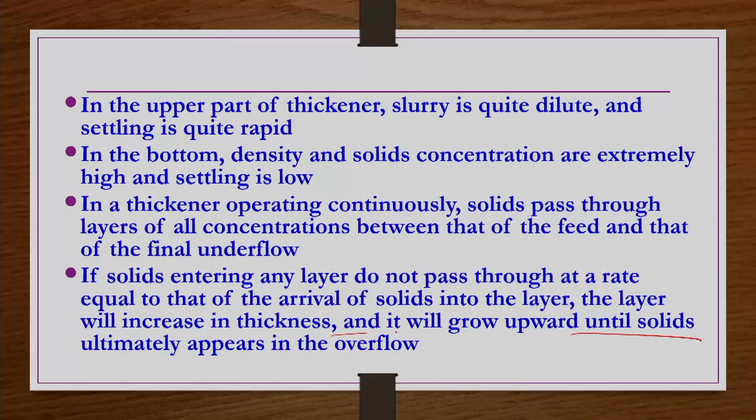So, whatever particles are coming into one layer, at the same rate, or even at a higher rate, those particles should pass through that layer. Otherwise, the thickness of that layer will increase, and then particles move upward, and eventually we will see particles floating in the overflow region.